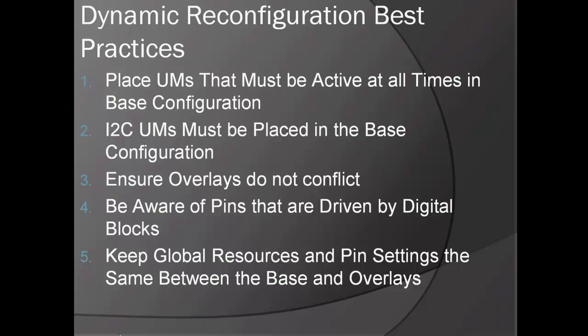Last, let's look at some simple best practices. Number 1, place all user modules that are loaded all the time into the base configuration. This helps to avoid accidentally unloading one of these user modules. Number 2, along the same lines, keep I2C in the base configuration. If I2C is loaded or unloaded, it will cease to function properly.